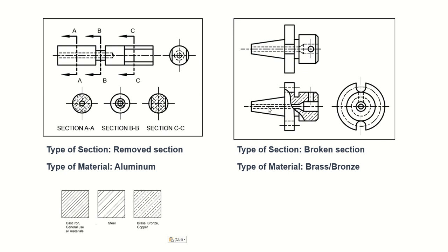You don't have to draw any of the sectioning on this side, because we're now using the hidden lines on this non-section area on this side. This is a little bit difficult to read, but don't worry about it too much. You're just cutting it down so you can see that, because this is broken that way. And the material, take it out, toss it out, and the internal surface is being exposed to you.